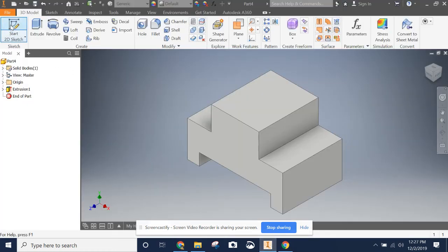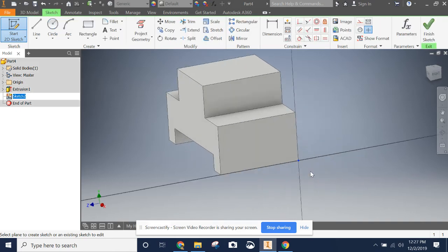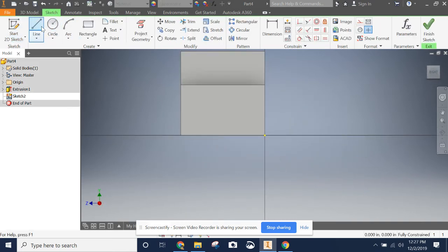So what we're going to do is start a new 2D sketch right here on this side. Notice how the side highlights. All right. I'm going to do a rectangle, and I'm just going to start in the middle. You don't want to start it on the edge because otherwise it'll snap and lock to that edge. We're going to just start it right here of, let me recheck our dimension, 1.5. Then I hit the tab key, and that'll jump to the next dimension to edit by 0.25 and enter. I'm going to hit escape to back out.